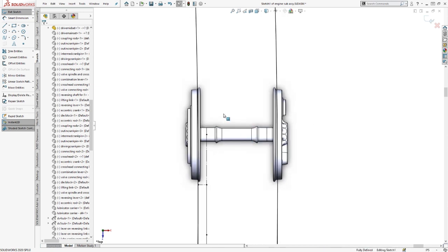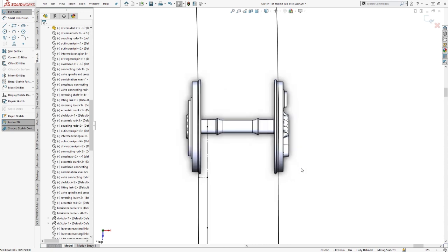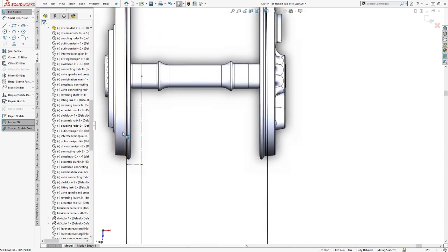Now in a train, you definitely can't spin a tire to make up the difference. You're going to have to figure out a way to differentiate, because spinning a tire can damage the tire and/or the track. Well, that's why this isn't a cylinder, it's a cone. There's not one set diameter.